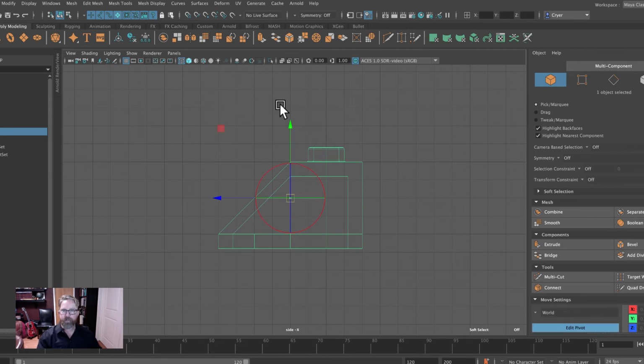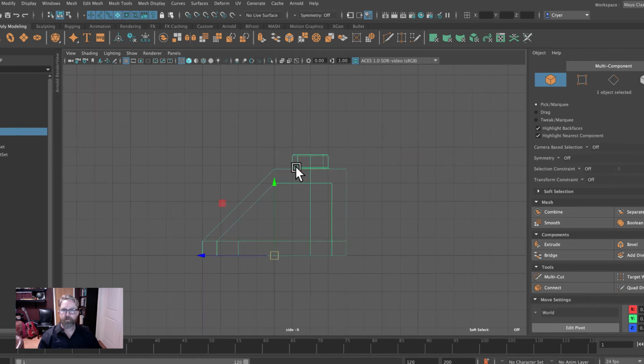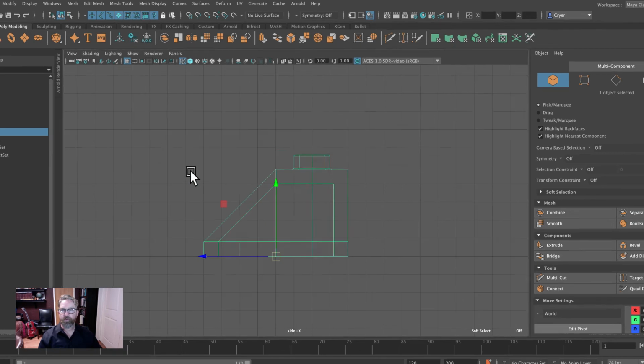and then I'll tap the D key, and we'll use that same technique, V key, middle mouse button, and it's snapped to the center bottom. And we'll tap the D key once again. We're going to grid snap the center to the origin. That's the best starting point. So we'll grid snap that up, right? So that is on the ground plane and also centered, right? 4 units this way, 4 units that way.